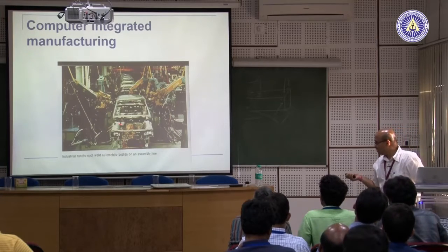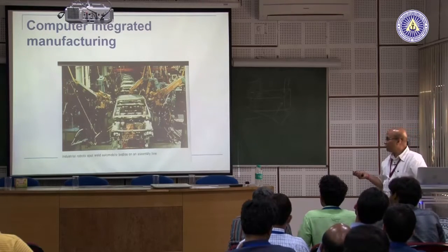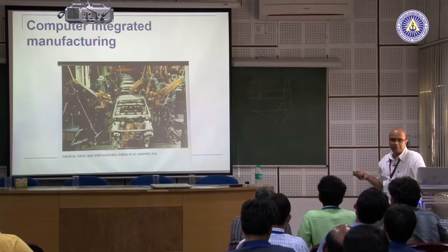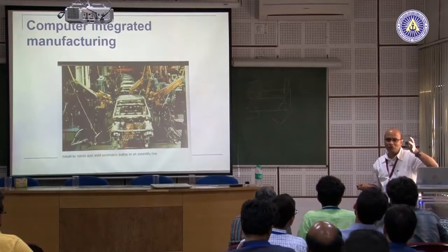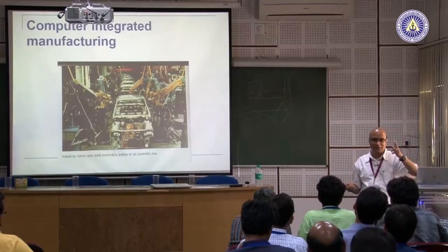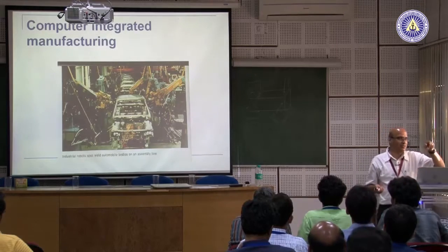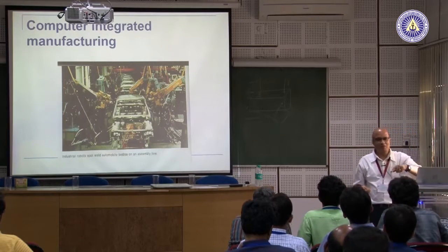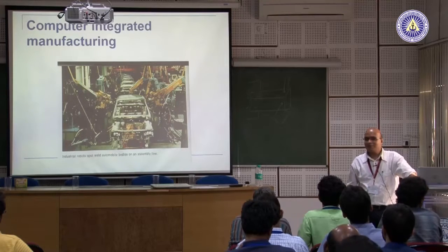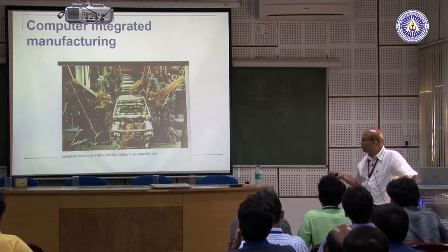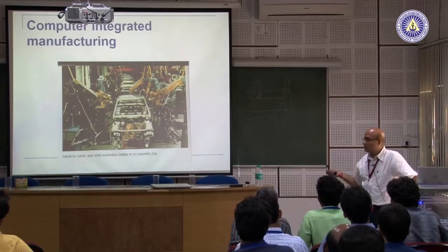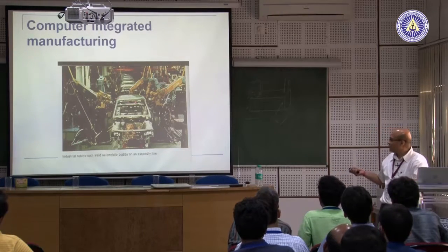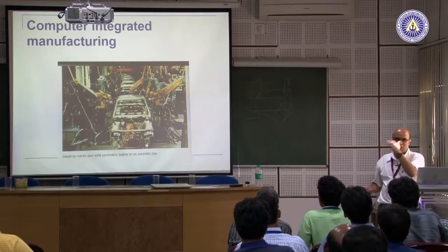So, this process is extremely complex, because first of all getting locations in space is not easy. We are saying get the coordinates of a point in space, which is actually very difficult, because no sensor will give you 3 coordinates plus 3 angles, 3 position coordinates and 3 orientations, 6 coordinates, no sensor will give. So, you can't get. Okay. So, what is done is, before making this assembly line, they would have a CAD model of this. Now, in the CAD model they will find out those points, okay, wherever the weld is to be done. Then the coordinates of that point will be output to the robot program.